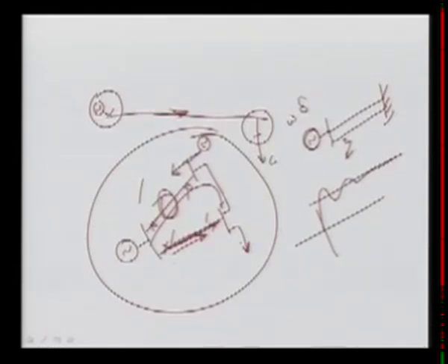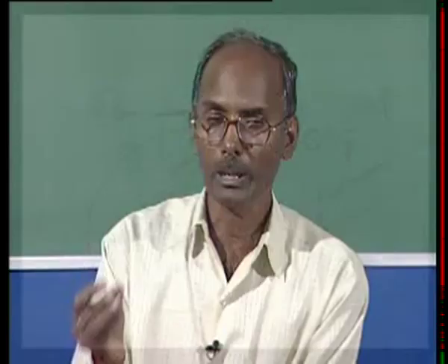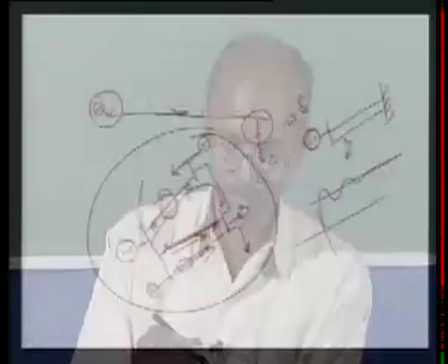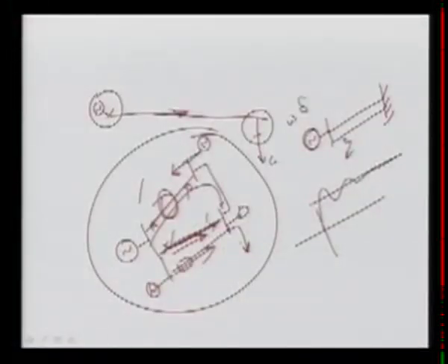There is a possibility we have another line here that is underloaded. So we can put even a generator here, and by putting some device here, we can control the power over this line, and then we can utilize it properly. So the FACTS controller may allow proper placement of the generators with the help of controlling the power flow in the lines.